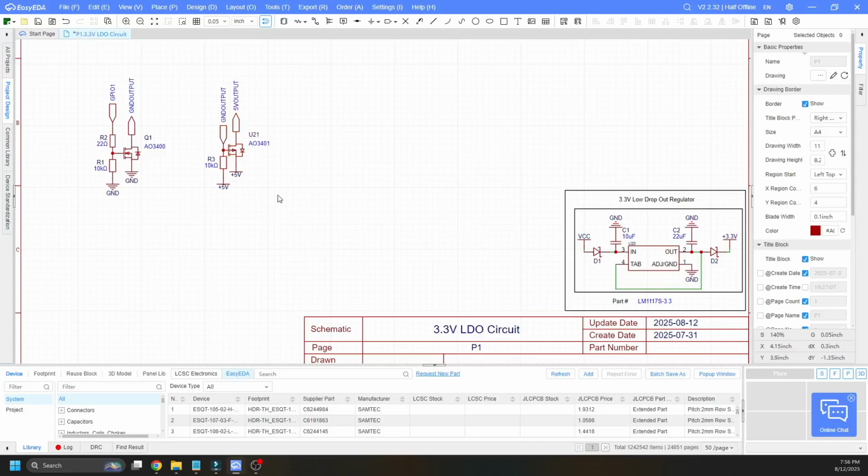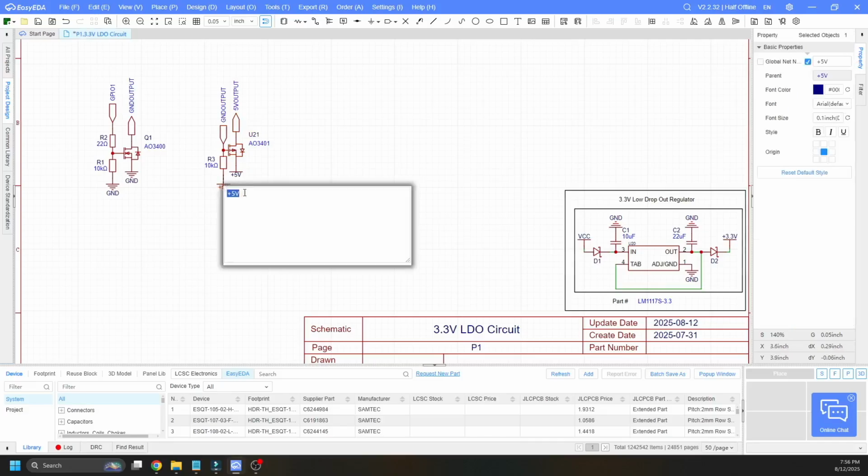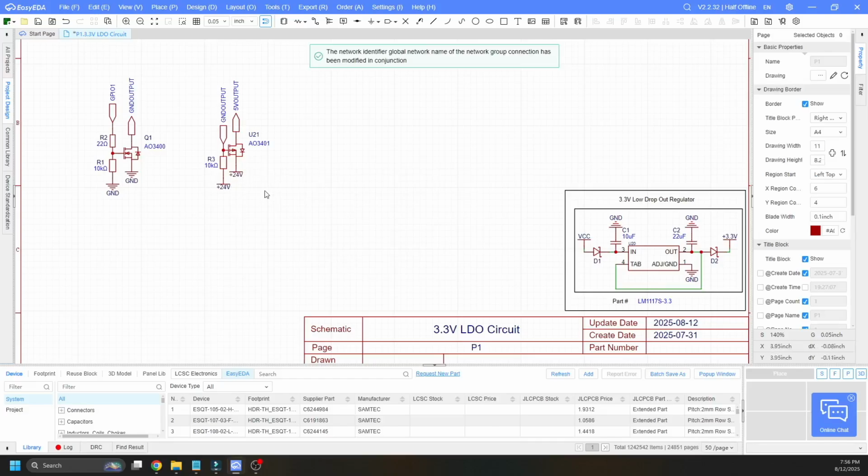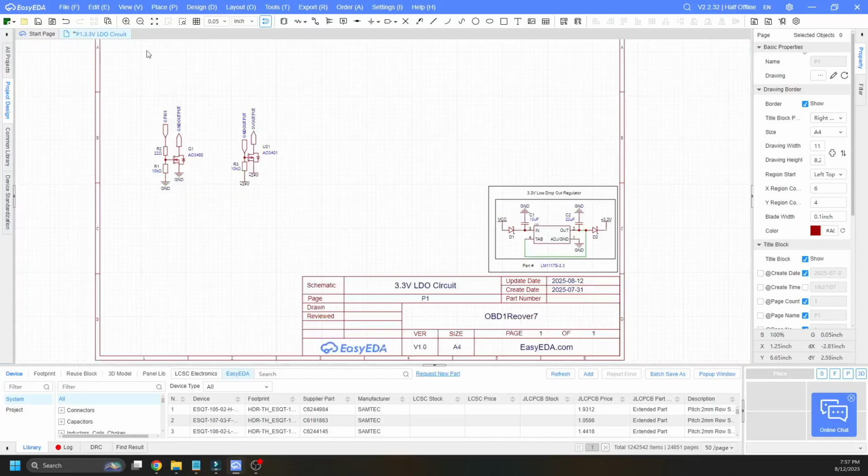So this configuration right here can be used for up to 30 volts. So why don't we go ahead and assume that we have a 24 volt logic. Using a microcontroller in this dual MOSFET configuration exactly as I'm showing you, you can actually use that microcontroller with a low logic level to turn on and off a 24 volt signal to your load for a motor, an LED, whatever it is you're using. So now let's go ahead and block it out just like we do the other ones.